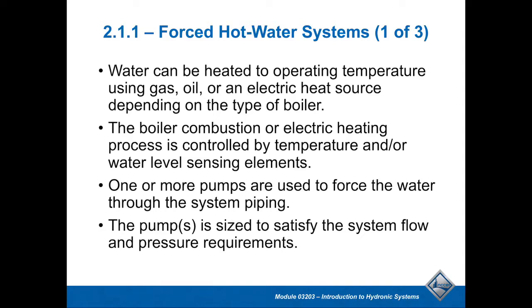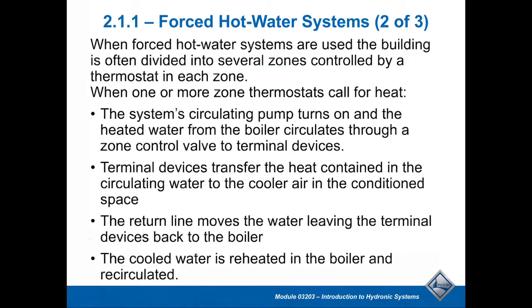Now, in the first series, we talked about how if we knew the BTU load of a structure on an hourly basis, we can very easily figure out the flow rate. Basically the flow rate helps us determine how big of a pump we need. So between the resistance of the piping system and the flow rates for the system, that's going to help us pick that pump. And that's what they mean by the pumps being sized to satisfy the flow requirements for that system. All right.